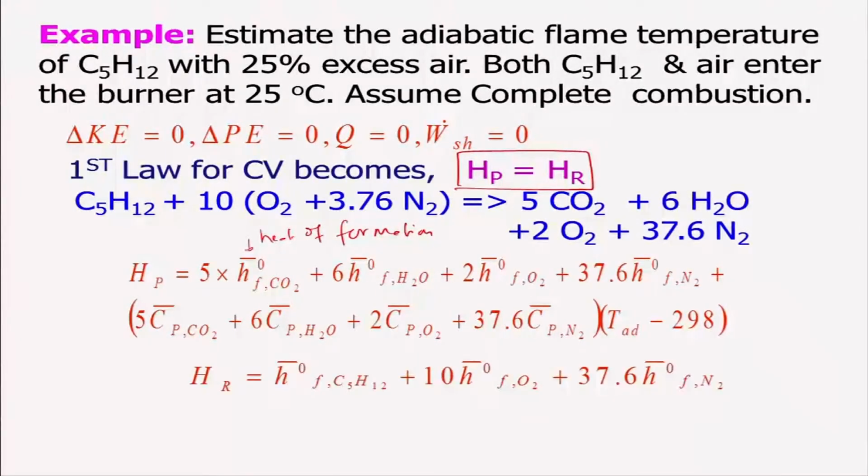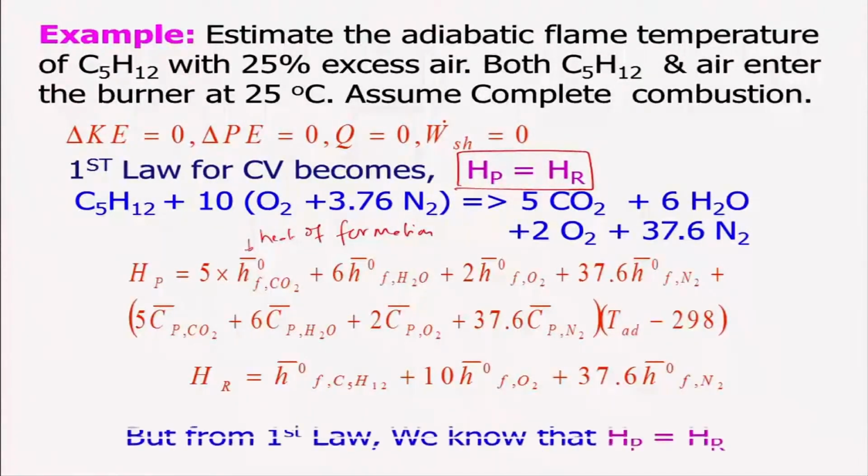And of course, Hr will be with the heat of formation, you can say all those for the pentane and oxygen and nitrogen, right. And there is no sensible enthalpy here, because it is at the ambient temperature to start with, right. So, therefore, there is no sensible enthalpy in this case.